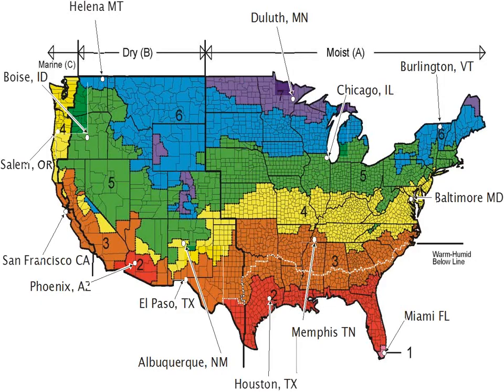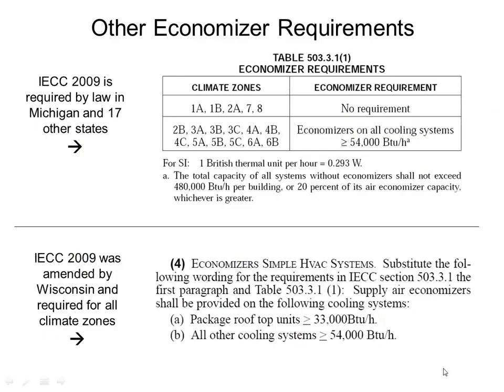And then Jonathan writes a question in, energy codes typically have a high limit shutoff temperature, but does this typically mean that you must economize up to this temp, or would 60 degrees be acceptable? I'm going to look into that question, Jonathan. I believe that means you cannot use economizer above that temperature, but I don't think it means you have to use economizer below that. And certainly if you go with an enthalpy economizer, then the rules would be different. But I will get the answer to that, and I'll put it up on the screen next week for all of you guys, so you can see that answer to that specific question.